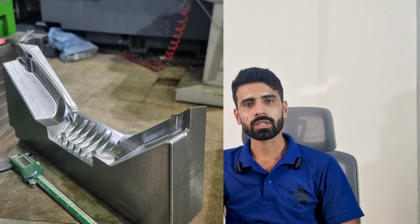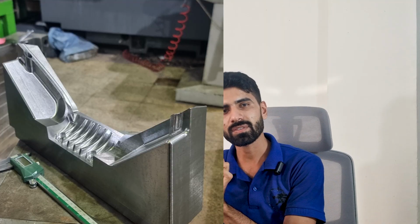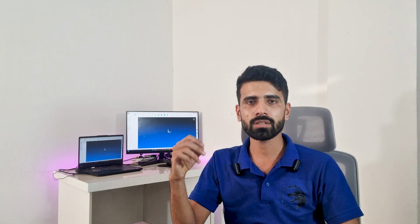you have to continue roughing with a smaller tool, not in all the space, but specifically in those areas which the bigger tool was not able to machine. You have to just detect those areas and machine them to make your piece ready for finish. As we talked before, for finishing you need a semi-finish. And what may semi-finish be?